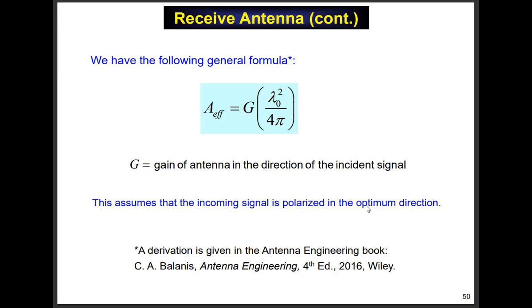Now, if the transmit antenna starts rotating, then the E field coming in is going to be tilted with respect to the receive antenna, and it's going to start picking up less and less signal, less and less power. If there's an angle theta of rotation like this, then there's going to be a term that looks like cosine theta for the voltage picked up, or cosine squared theta for the power delivered. So there's a loss in power delivered to the receiver by cosine squared theta.